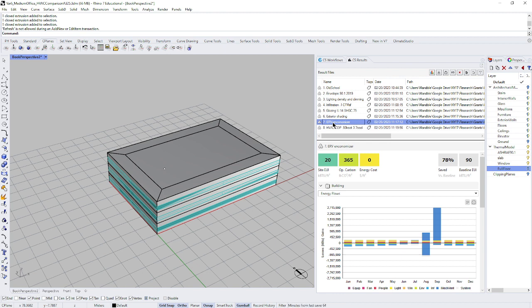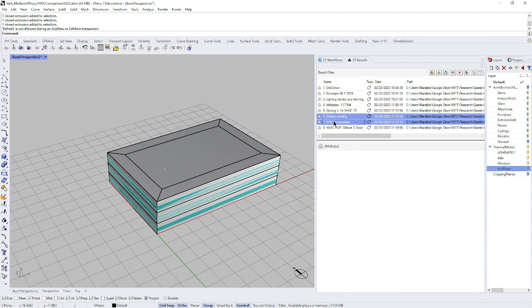An economizer cycle is simply a setting that says we're going to turn off the heating and cooling coils, or whatever it is that we're using, when the outdoor temperature is in the correct zone, so we can just bring in fresh air without having to heat or cool it. So anyway, from where we were before, a pretty large jump to 20.